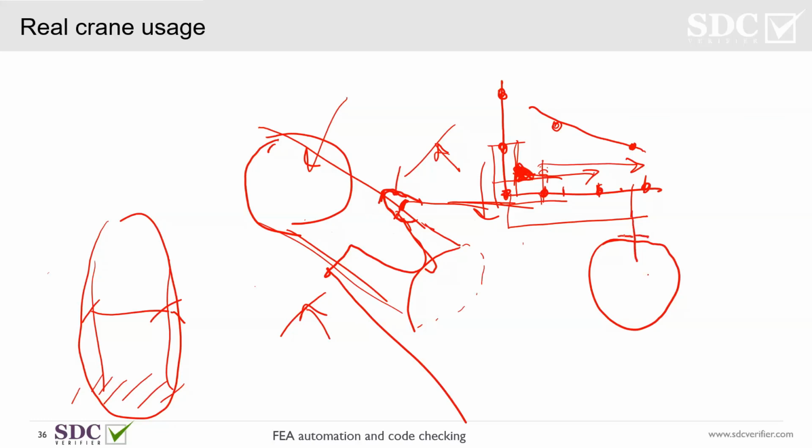And then what you can do is simulate the weld used for this pipe with a separate row of elements. When it's done, you can assign the appropriate notch class directly to these welds, because apparently this is a welded part, and this extra row of elements will simulate your weld. Well, this part is going to be a non-welded part of the structure.